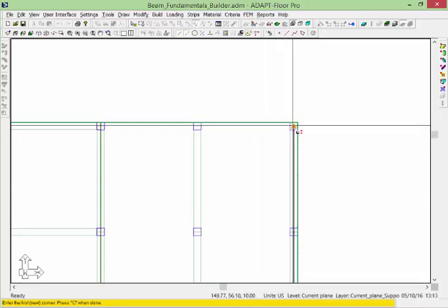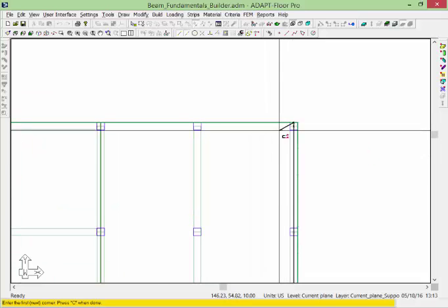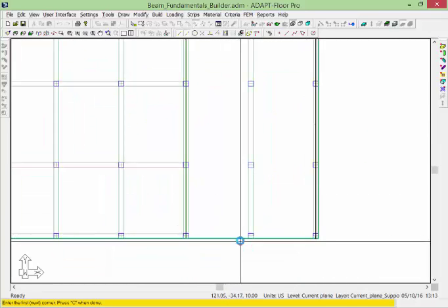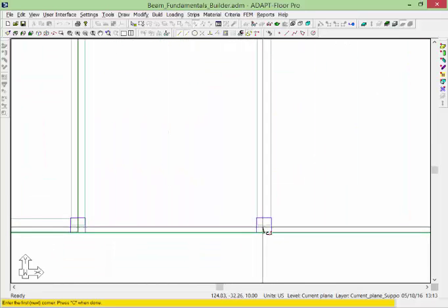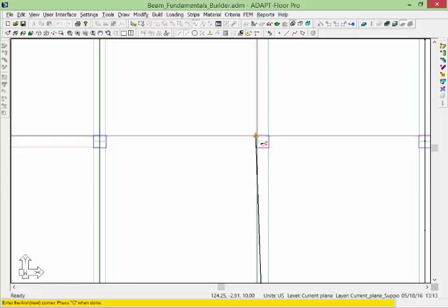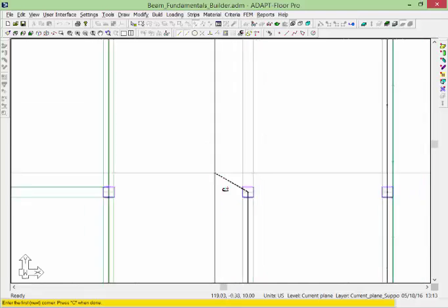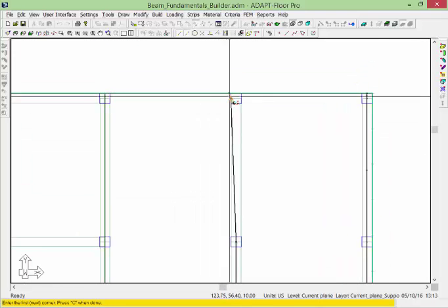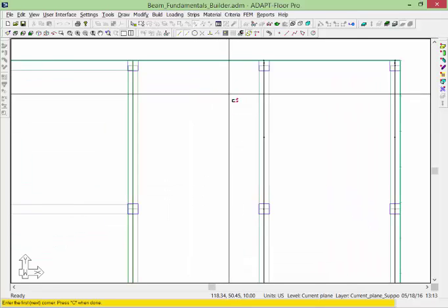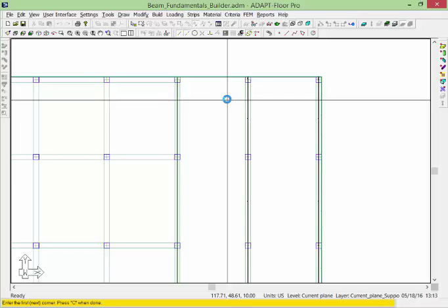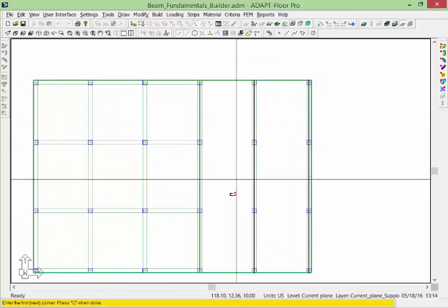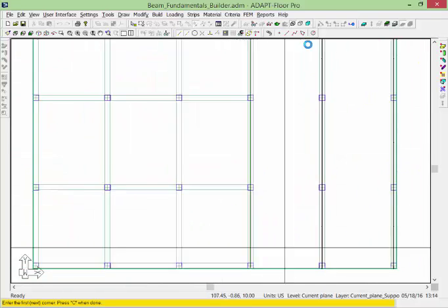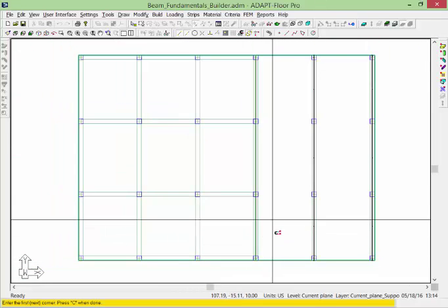And notice that the beams are also snapped to the center lines of columns in this case. That's probably the most fundamental way that you can enter the beam geometry. Realistically, the beam is not that long, but analytically, again, this may be the easiest way to model the beam. The program does support you modeling beams anywhere in proximity to the column, but again, for this case we'll simplify and use this option for centerline modeling.